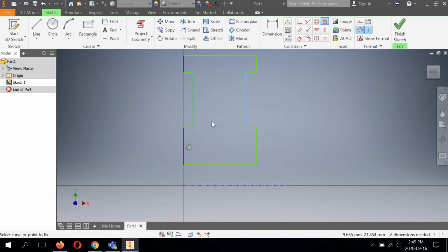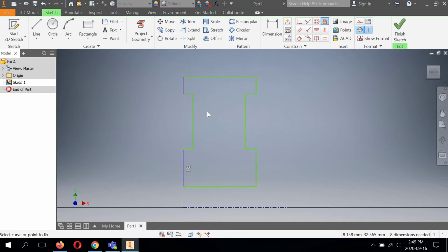All right. So next, we can add some constraints to this. And I'm referring to this on my iPad as I do this. So I'm not going to be toggling back and forth to each screen to show you the sizes of these things. When you draw these things, you need to reference these things on your iPad next to your computer. Have your iPad hub open to the particular module. So from here to here, we'll constrain to 3, and we'll do the same thing on this side.